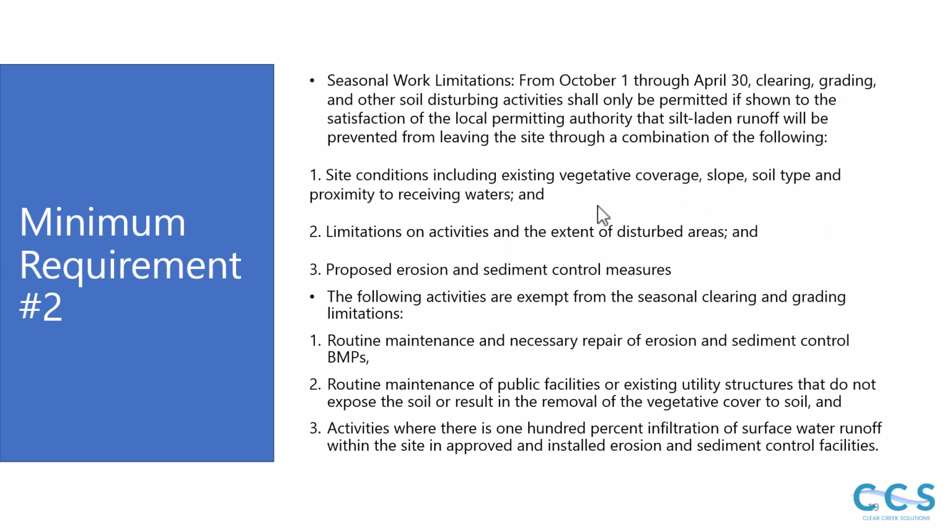For seasonal work limitations, from October 1st through April 30th, clearing, grading, and other soil disturbing activities shall only be permitted if shown to the satisfaction of the local authority that silt-laden runoff will be prevented from leaving the site, because these are the wettest months of the year. This considers site conditions including existing vegetative coverage, slopes, soil type, and proximity to receiving waters, limitations on the extent of disturbed areas, and also proposed erosion and sediment control measures.